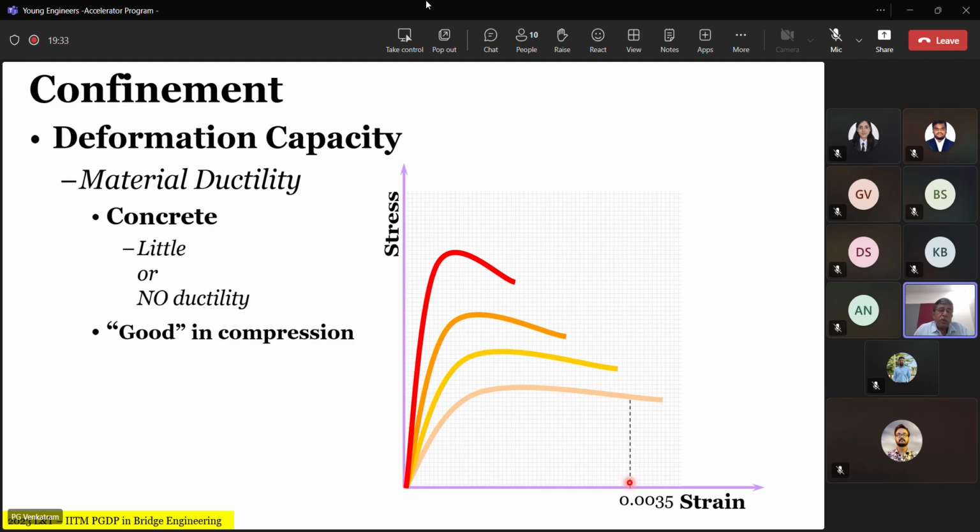For all our design philosophies, we use what we call the constitutive relationship, which you all understand. It is the relationship between stress and strain for concrete, in terms of a parabola up to a certain height and a line parallel to the x-axis thereafter. To define that constitutive relationship, we use it up to 0.0035 because this is the maximum reliable value that we have generally seen from the lab. Otherwise, it can go a little higher.